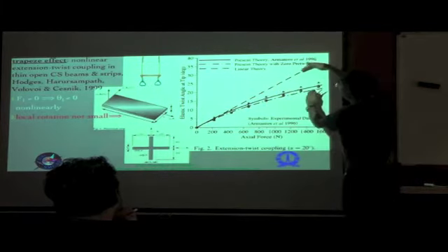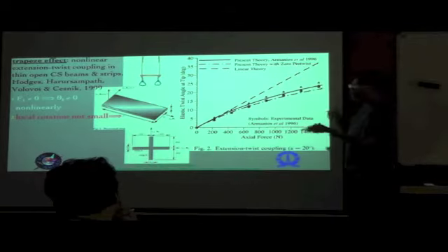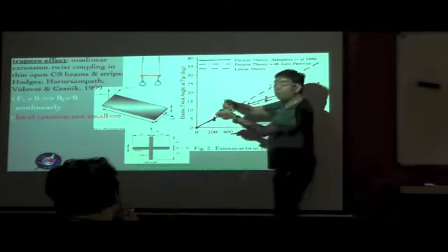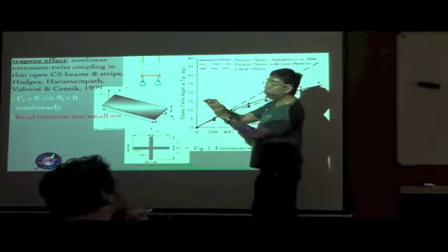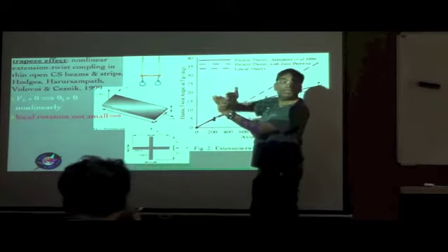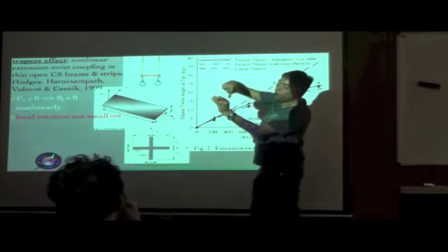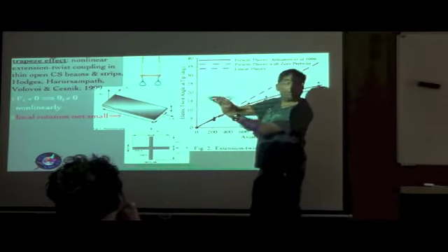That is the difference that we are talking about between a linear theory and a nonlinear theory. Why it happens is primarily because of that so-called local rotation, as opposed to a rotation of the cross-section itself in any of these directions. We are talking about a local rotation of a line element which is perpendicular to the plane of the strip.